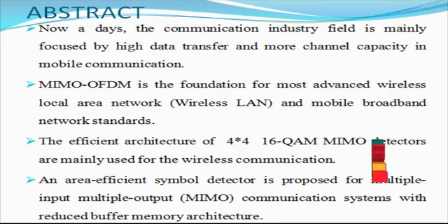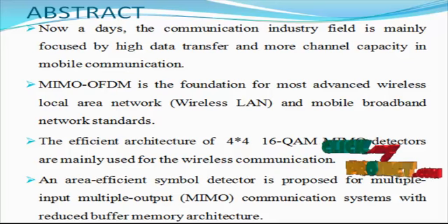Several designs have been proposed for SC-FDMA MIMO detectors, among which the linear frequency domain equalizer FDE receivers, including minimum mean square error and zero forcing, are often used. Successive interference cancellation and iterative techniques can be used to enhance the performance of FDE receivers. This paper introduces a novel low complexity MIMO detector tailored for single carrier frequency division multiple access systems, suitable for efficient hardware implementation.